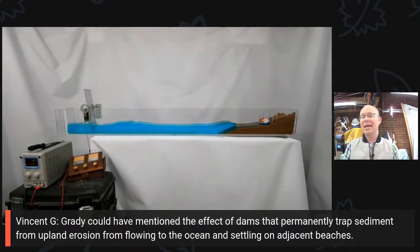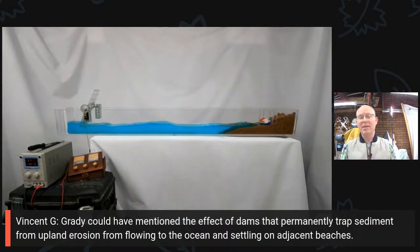The major point is that humans have had a dramatic impact on the sediment supply coming from the upland or continental areas and making its way down to the ocean. We've done that through damming up of major rivers. When you create a dam and a reservoir, you slow down that flow, which allows the sediment that's inside to drop out of suspension. One concept that's kind of hard to understand, but really important here, is that the more sediment that's carried within a stream of flowing water, the less erosion that water can create. The water can only hold so much sediment.